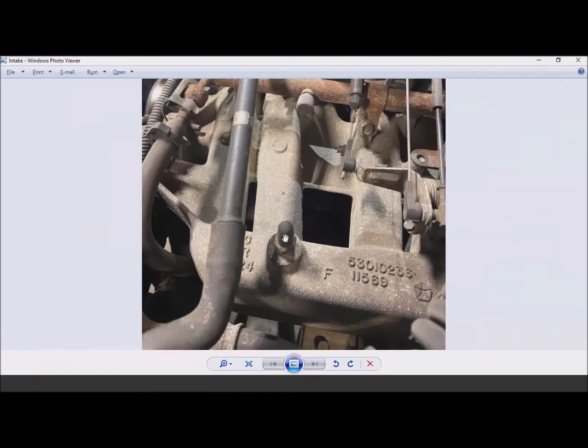So, you know, think about it. If this vacuum cap cracked or were missing, I guess on this engine, it would probably affect cylinders 1 and 2. It would have no effect really over here on cylinder 3, right? Because the air's coming in, you know, through the throttle body over here. But as the air flows through to cylinders 1 and 2, and this extra air is being drawn in, those two cylinders are going to be exceptionally lean, and they're going to misfire.